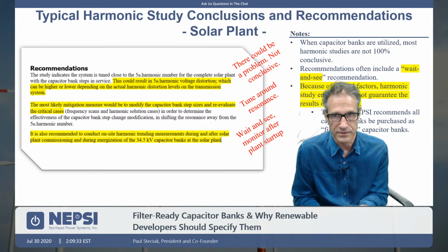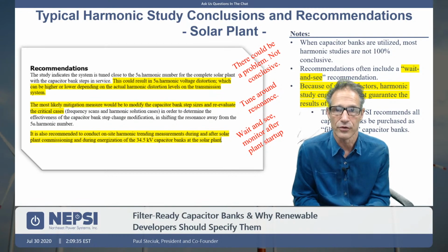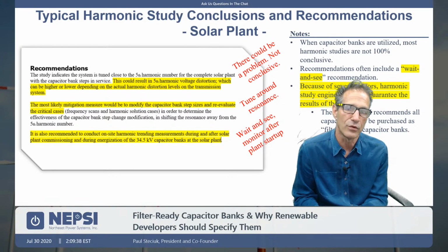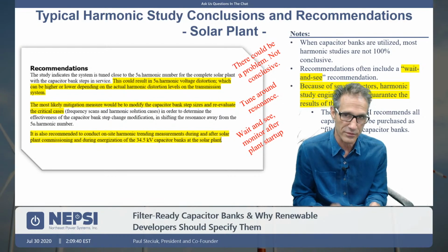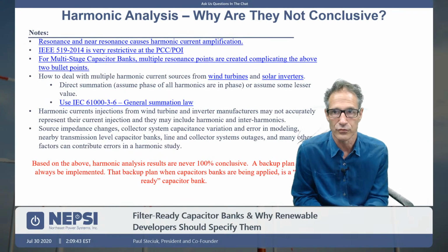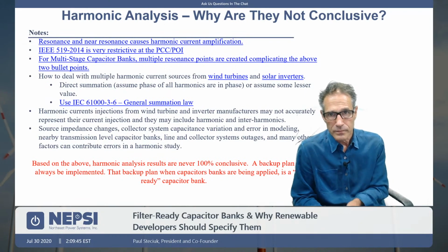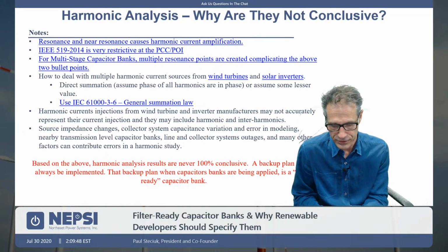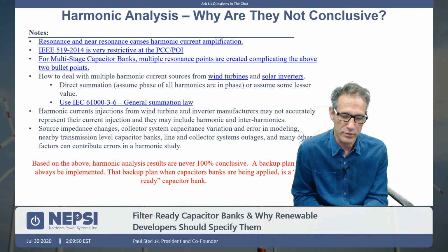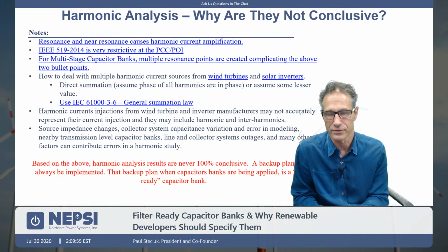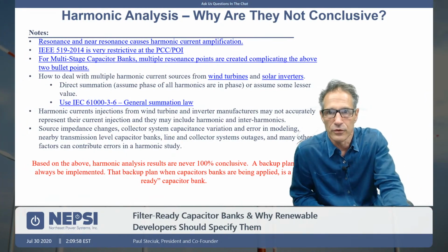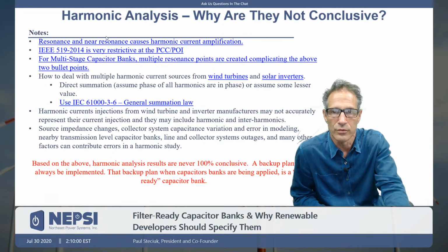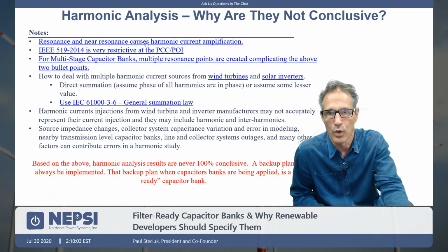So this solution is not the greatest, and it is one of the reasons why NEPSI always recommends filter-ready cap banks, and that's what we're going to be talking about today: filter-ready cap banks. One of the first issues that we see is that harmonic analysis results are most often very inconclusive. We're going to go through each one of these points one by one, and I will briefly touch upon why these are contributing factors to a harmonic study being not conclusive.